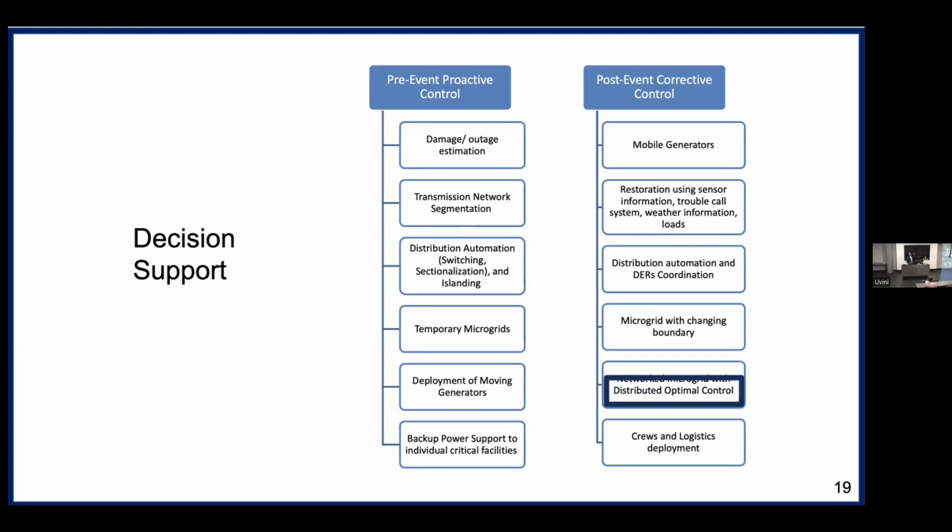And during these events, it is not only the power grid, with all these distribution lines being impacted, but it's also the communication line. And if the network and communication line is impacted, you cannot send the data from, let's say, a DER to the control center. So in that way, distributed control is useful because it does not need the data from location A all the way to the control center, but you can exchange data among different nodes, and then it can still solve the optimization problem, right? Of course, we can always resort to local control, which is using the measurement and then taking the control action, but it's not optimal. While with distributed control, which only requires data to be exchanged with the neighbors, we still get the optimal solution.